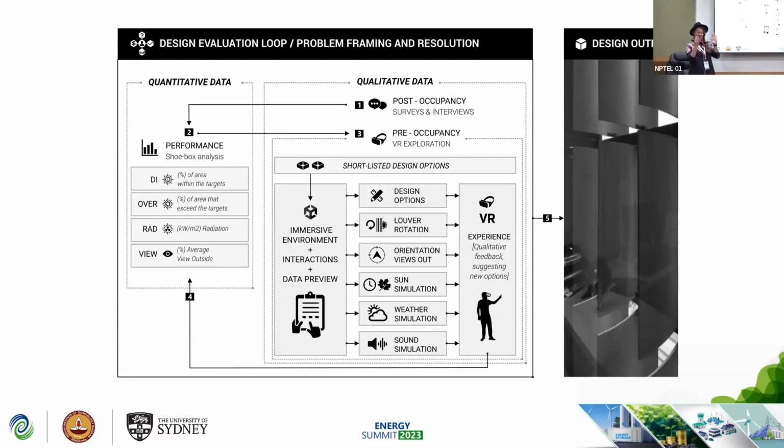The facade louvers were originally designed to be kinetic, so they would rotate, and people could choose whether they wanted them open or closed. Great idea in theory. In principle, it's good, but in reality, they all broke after about one or two years, and some offices had completely shut down the blinds for a long time. So they decided to redesign them and make them static, calculating the best closure or open angle for best performance, so that you don't have to spend too much energy to cool the building and it allows natural light in.